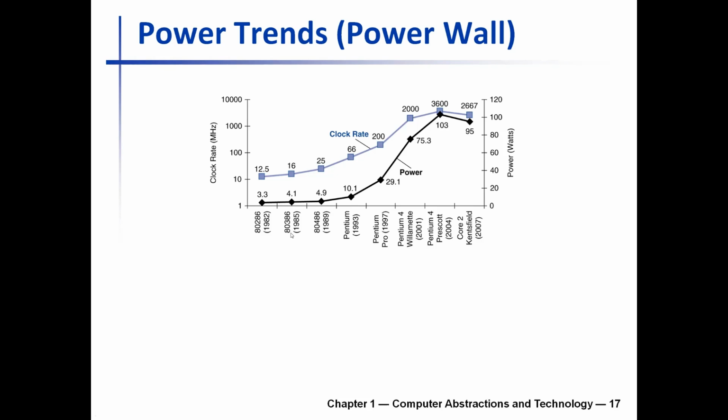The time required to switch the transistor kept getting smaller and smaller. So per second, the amount of power you need is more, even though the amount of energy you need to make a single switch is smaller, you can do so many switches per second that the amount of power required by the chip becomes higher, right? Simple logic.